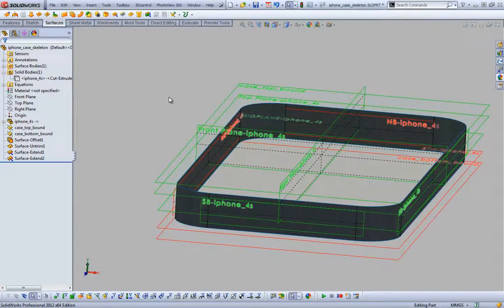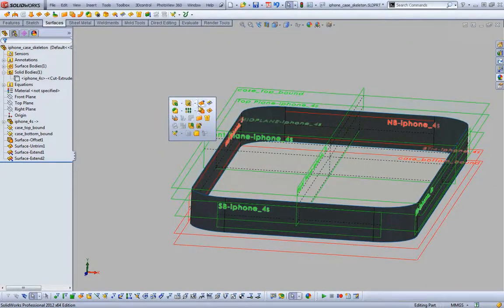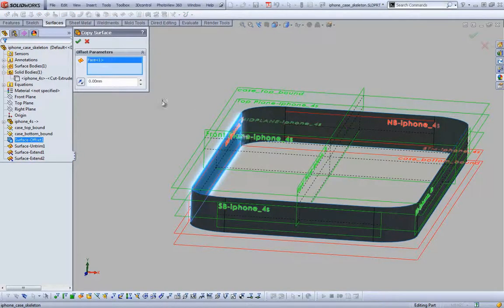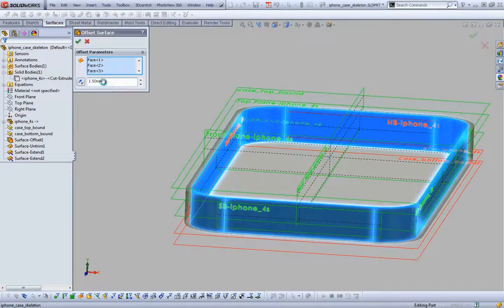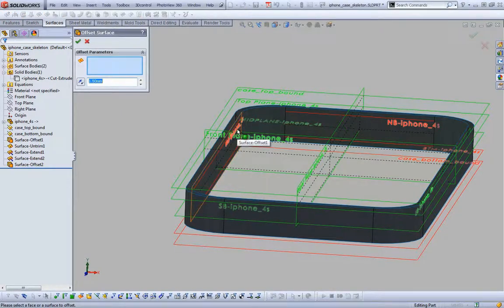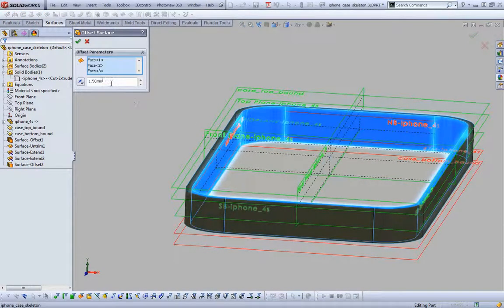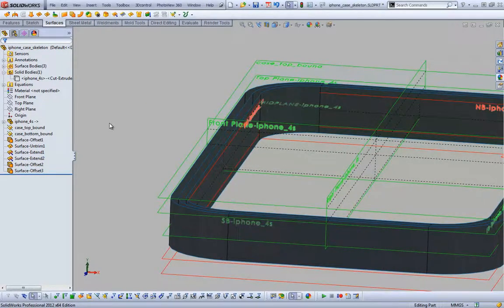So then we're going to need a couple copies of this. First of all, we are going to need an offset of this. Select tangency of, we'll set that arbitrarily to 1.5 for now. We'll hook it up in a second. Select tangency of 3. So there's a couple offsets.